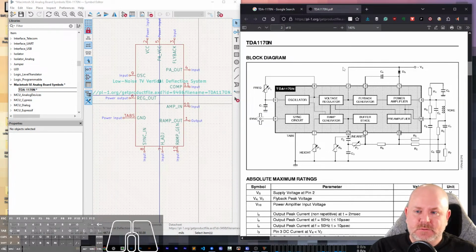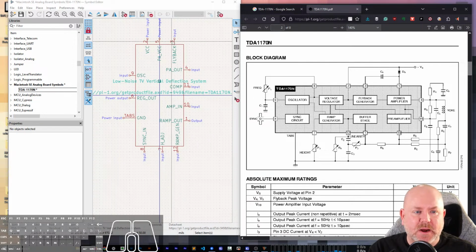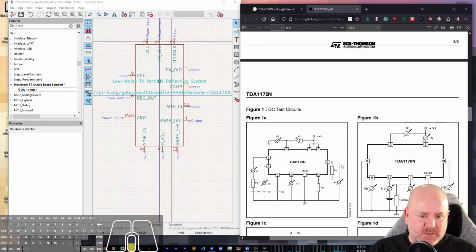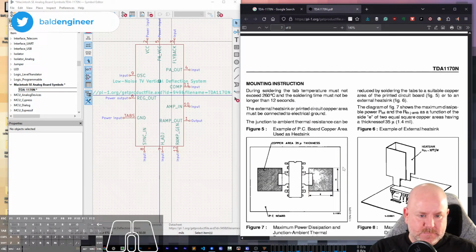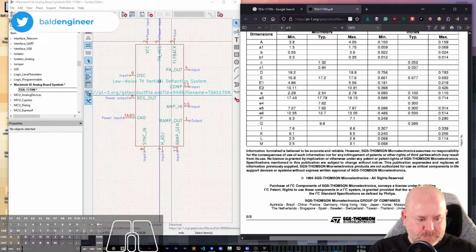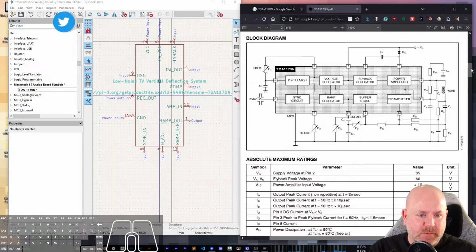All right, so 2 is input, 3 I wonder if 3 looks like an input as well, doesn't it? Yeah. I wonder if it's a power, no. And then 5 is a, yep, so 3 is definitely an input. It might actually be a power input, but I'm not sure. Do they have a pin description? That's what I should really be looking at. No. But 3 definitely, to me, looks like a power input.